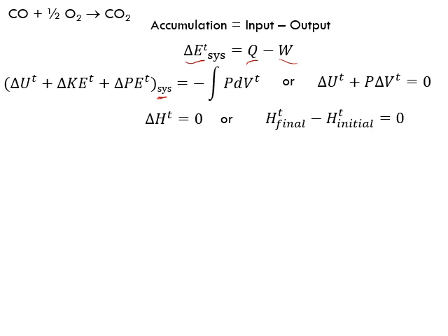And then we are saying we're running adiabatically, so Q goes to 0, and we have the boundary work, that is the work related to the expansion and contraction of the boundary. Here is the integration of P dV total, or we can carry out the integration. P is constant, goes outside the integration, and then we have here P delta V, and from the left hand side delta U. So that's how we write it.